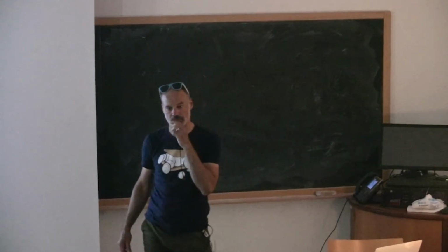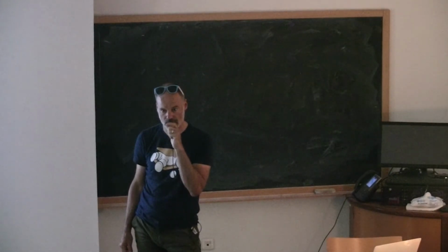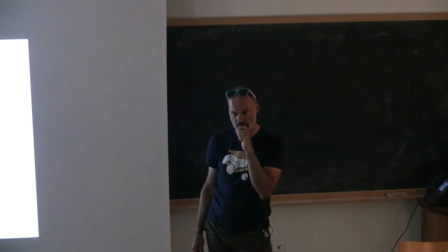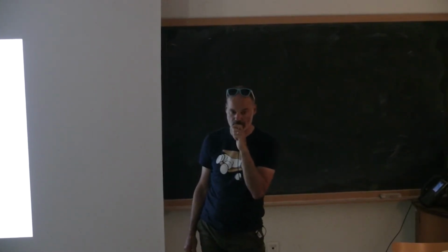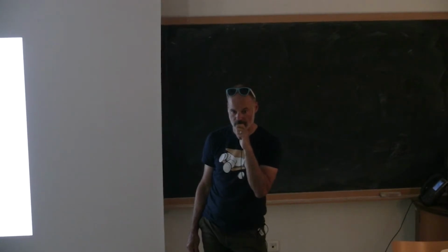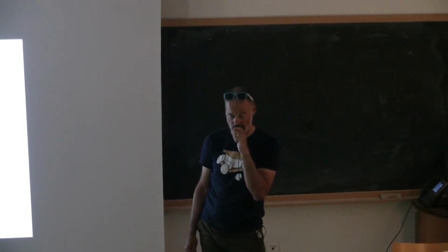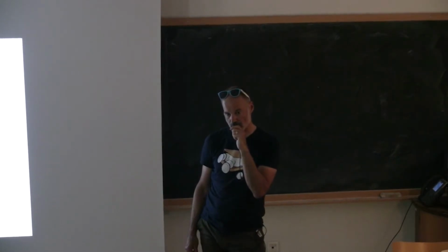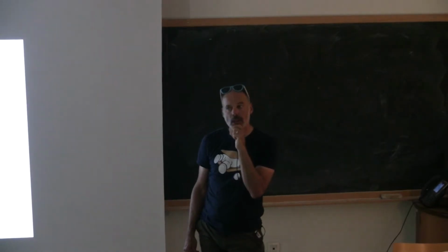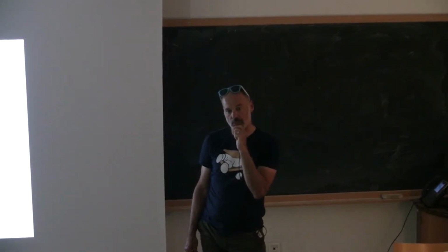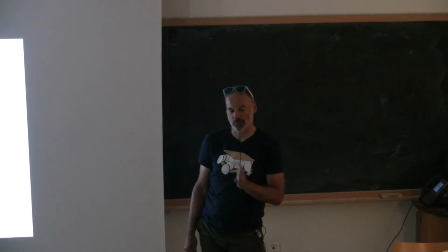John, did you have a question? Yeah. You've focused on conductivity, but sorptivity really controls infiltration for the first capillary length scale, which is typically about 30 centimeters of soil or so. And the sorptivity, instead of going with the square of the particle size, goes with the square root of the particle size. So it's much more uniform than is saturated conductivity. So the first thing I want to do is have you kind of reflect on infiltration processes and the fact that sorptivity really limits heterogeneity as a player. So, okay, finish your question and then I'll start answering.